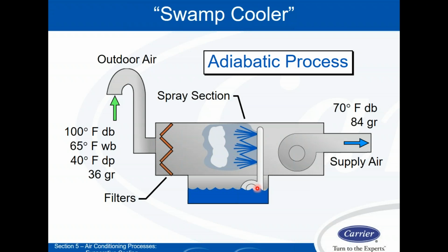I run them through this air handler where I'm misting water into the actual airstream itself, directly adding it. This would be direct evaporative cooling. There is also a thing as indirect evaporative cooling. That would be a different discussion. Right now, we're directly adding the moisture into the airstream, so it's direct evaporative cooling.